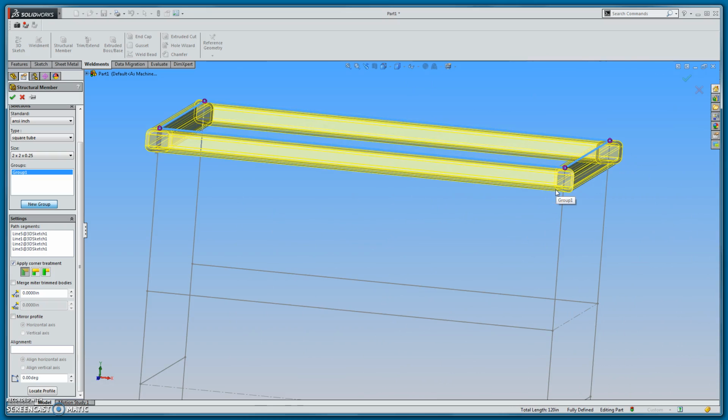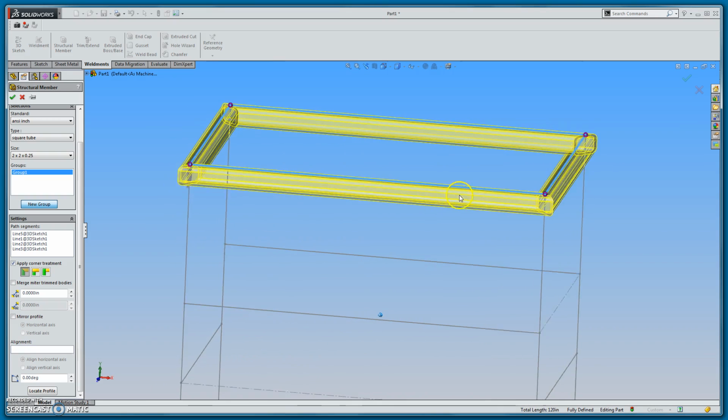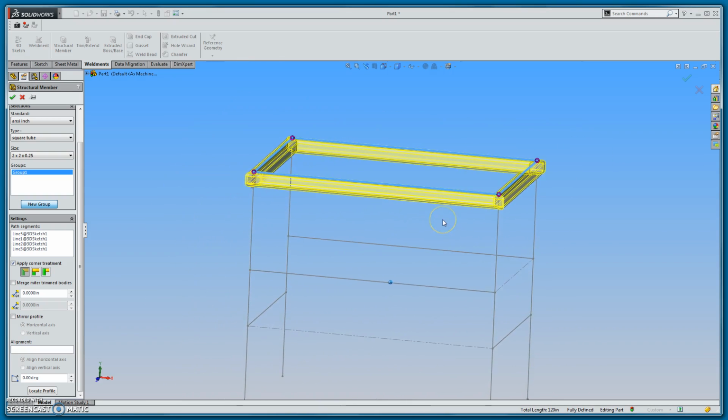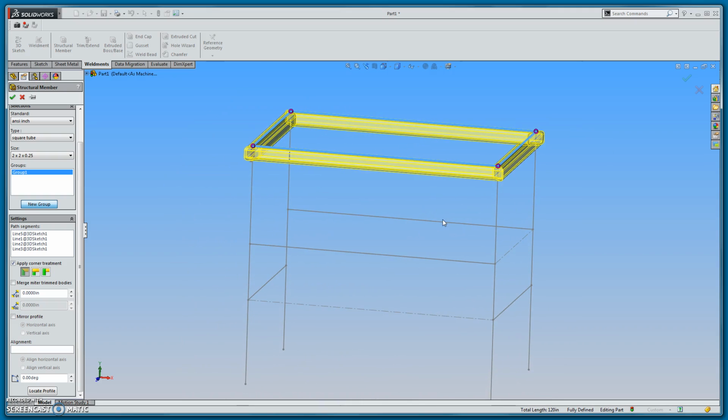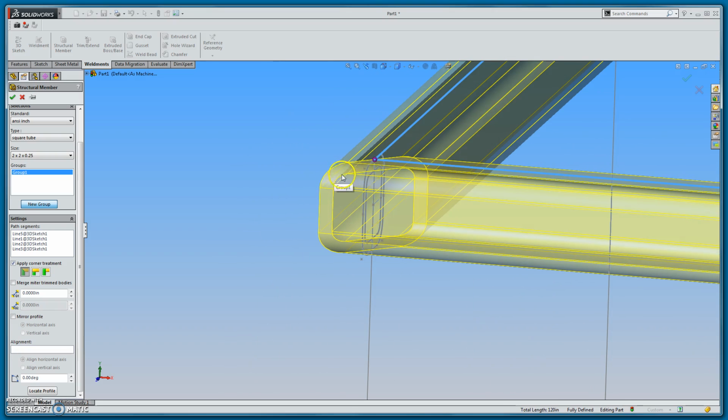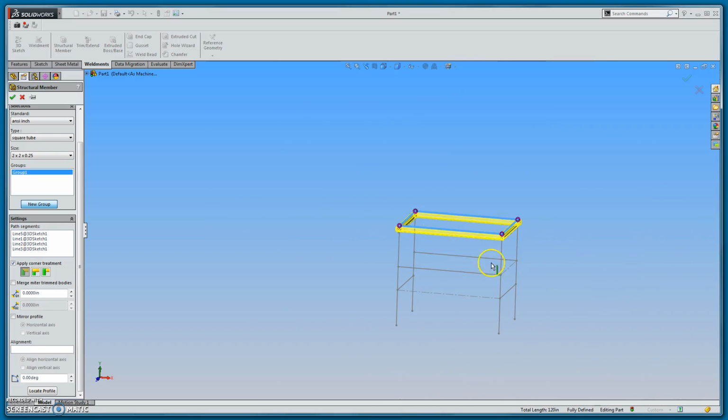So initially it grabbed the center line, so that 34-inch height that I gave it, I had to add another inch, because remember I was in the center of the tube. So my height would have actually been 35 instead of 34. So in this case you could see how locating the profile down changed that. Again, if my 12 and my 24 were critical, I might want to push them in a little bit and grab the corner, but in this case I'm going to let it slide.